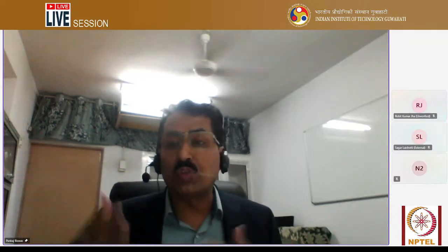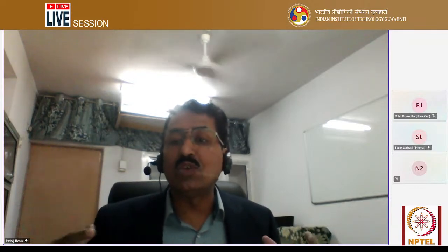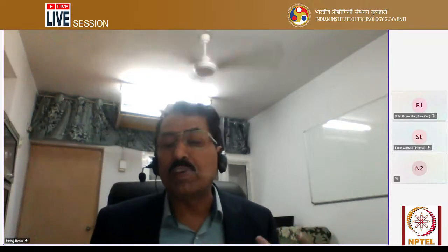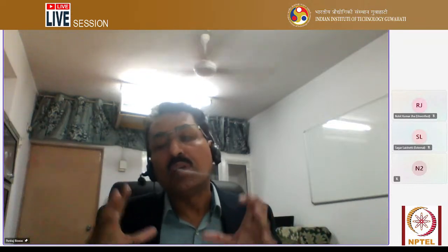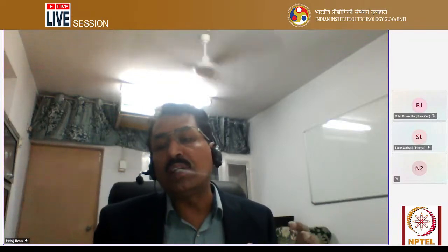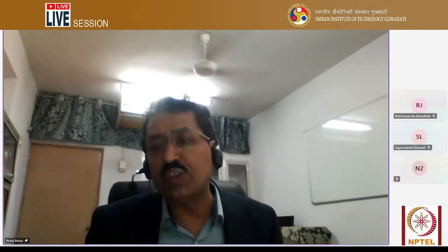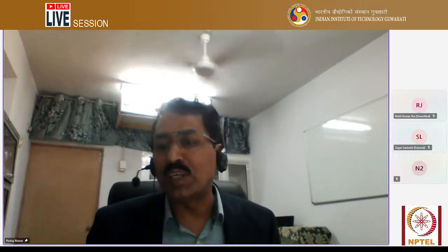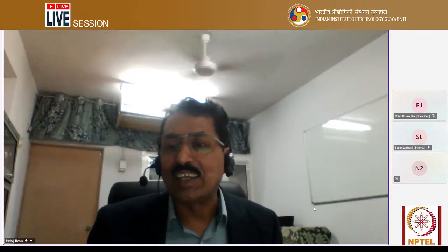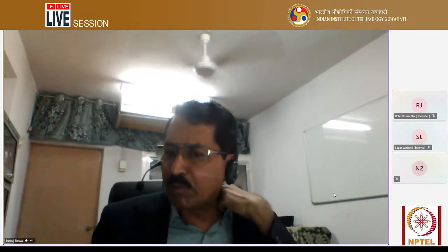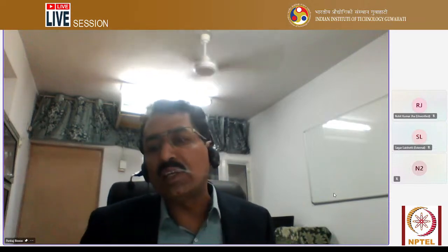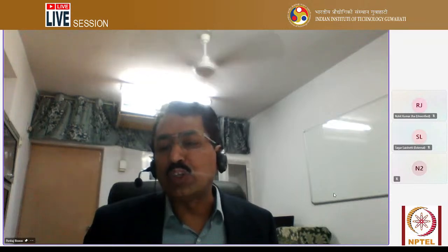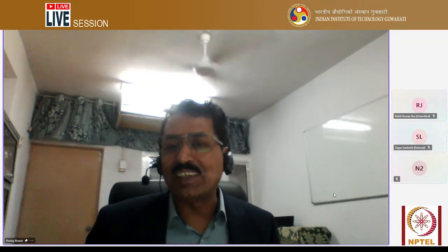Apart from this, if you want to further improve the quality of the weld joint, you can use some auxiliary setup where there is a further supply of some inert medium, or you can also incorporate some flux if required. By this you can protect the weld pool. So depending upon your requirement, you can decide what precaution is required for that. Understand, Sagar?